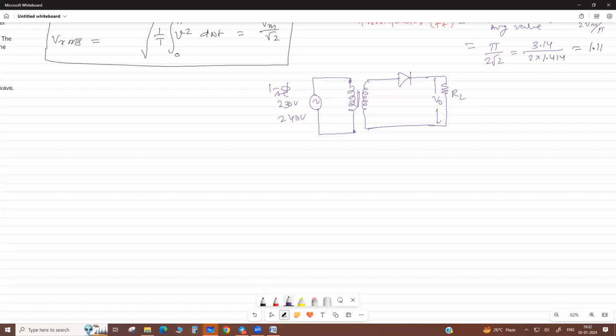It is a DC output because it is after the diode. Before the diode, here is also AC. Here also AC. Okay. Here you get a DC. Here is the source voltage. And this is the source current, input current, and output current, load current. Actually the currents are the same because it is a series circuit, but output voltage we measure across the load resistor, and this input voltage is AC. Okay, this is also. तो हम इसकी बात नहीं करते हैं. We have only this much diagram.